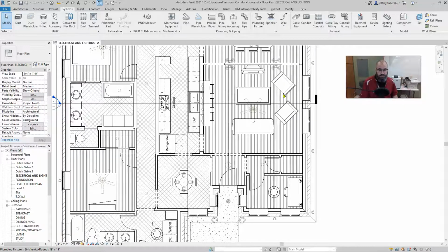You have to think about what people are going to use in these certain rooms. A living room is obviously a lot of times an entertainment center. It could have a lot of different electrical components: TVs, DVD players, DVRs, video game consoles, things like that. So you need to provide enough for that. You also have to think about how they are going to clean this house. They might have a vacuum cleaner or a buffer, and they're going to have to plug in at various different locations. So the rule of thumb to take care of all that is to make sure that you have at least one receptacle on every wall.